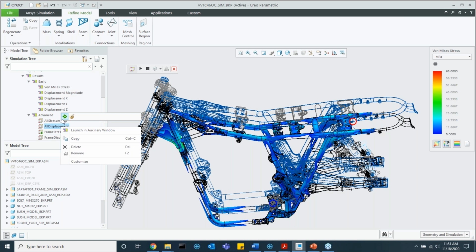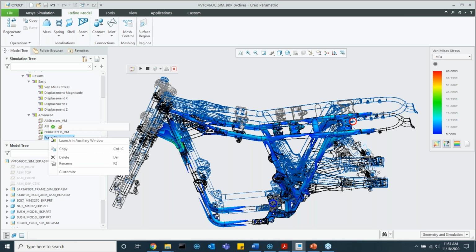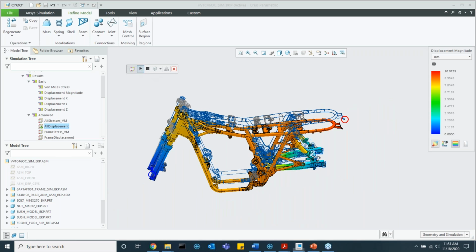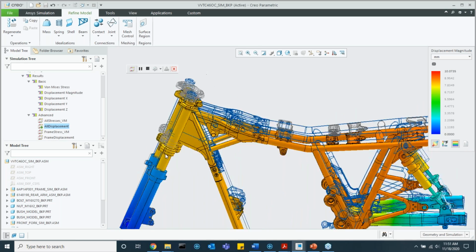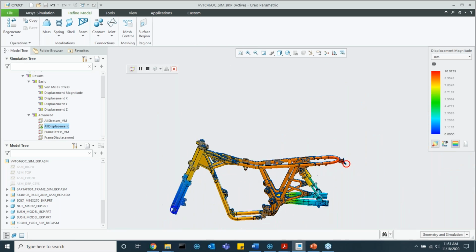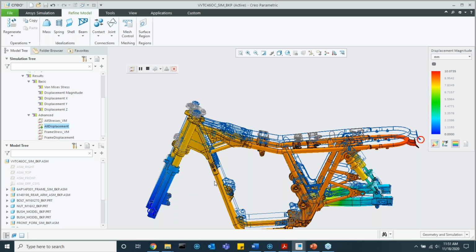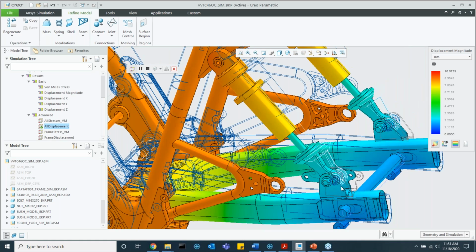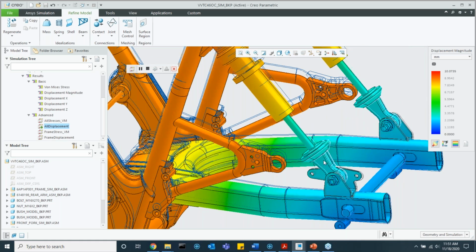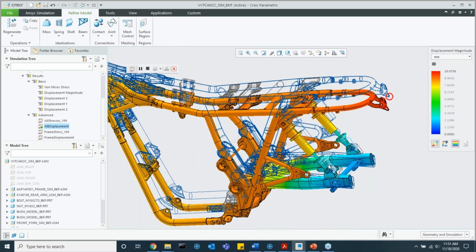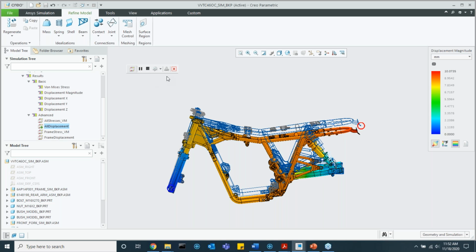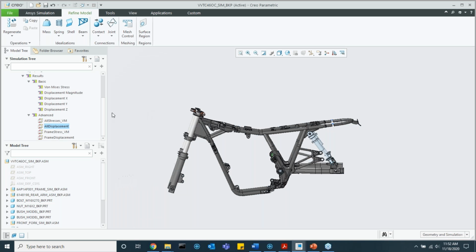We can also show displacement. And again, this is going to show an animated version. So I'll show the all. Give it a moment. And if we animate it, we'll see those joints really matter here because we'll see the shock tubes are basically moving down inside of where we prescribed that they can move. We can see that over here as well. So this one's a good view because we have a hinge support as well as this pushing down. And we see how that all works together because we prescribed that in our simulation. I'll close this again to exit the result.